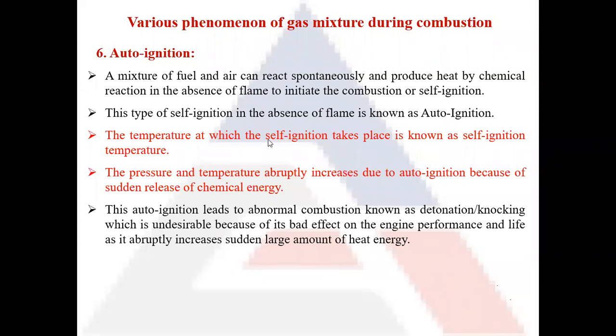The temperature at which this self-ignition takes place is known as self-ignition temperature. The pressure and temperature increase abruptly during this auto-ignition because of the sudden release of chemical energy. And this auto-ignition is the cause of knocking or detonation